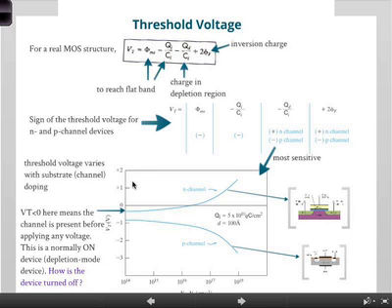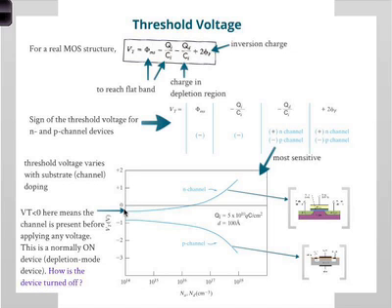What's more interesting is looking at the N channel. The P channel is very simple, logically straightforward. N channel is much more interesting if you think about it. When the doping is very low, which is, by the way, most of the time, because you want to have a lightly doped substrate. You don't want it to be very heavily doped. Why, by the way?